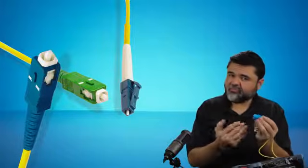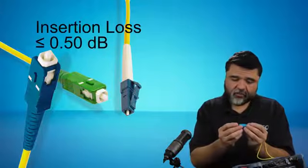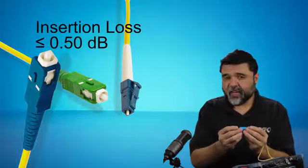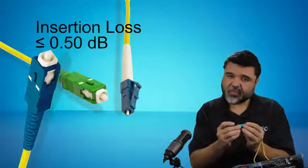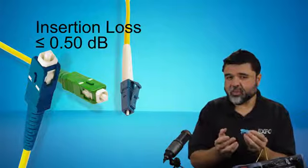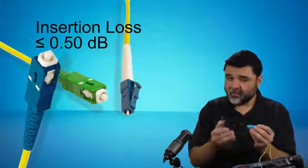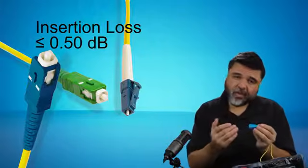So most connectors today, your insertion loss is about 0.5 dB or better, roughly. And so it can be as high as 0.75 per mating. It really depends on your specifications, but a lot of the companies that I work with are looking for 0.5 dB of loss or less on a physical mating. And so that's just one of the values that we look at.